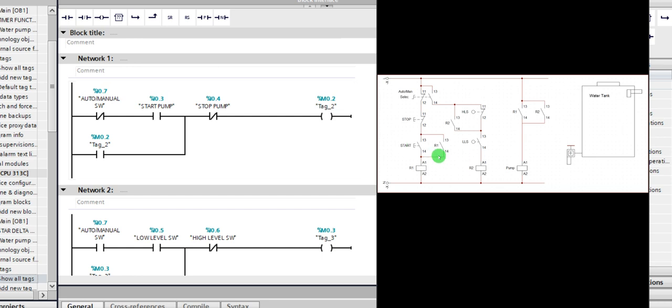This is the ladder logic. Now I latch this particular relay using my relay contact here, the same way I latch this coil using this one. But here I'm using an internal bit of the software. There I decided to use a relay because I'm working with the physical structure of my component. But here I don't need the physical component. What I need is the logic, the internal bit, so that I will not end up having multiple outputs. In order to minimize my output usage, I will use internal memory bits to make multiple-bit control instructions. So this is not actually an output, but a coil, an internal bit coil.